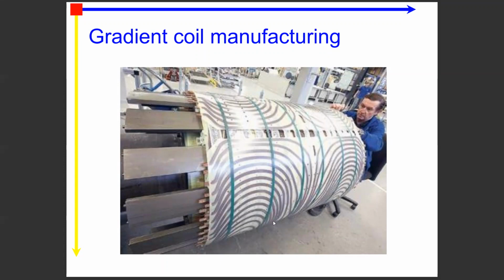They're flowing through a static field produced by a superconducting magnet, and if you have charges like electrons or holes flowing through a magnetic field, using the right-hand rule, you will realize there will be a force acting upon those charges. That force, the Lorentz force, will be very strong, and it will twist and torque the structure every time you go positive and negative in the pulse.